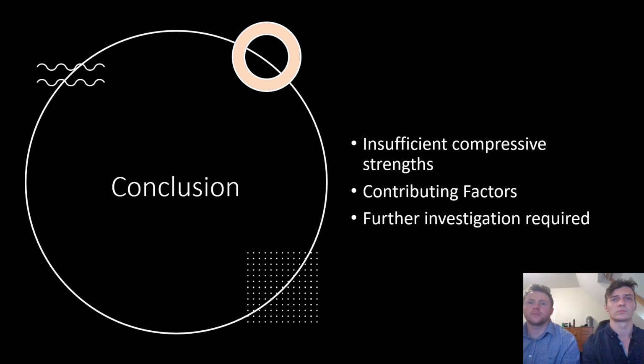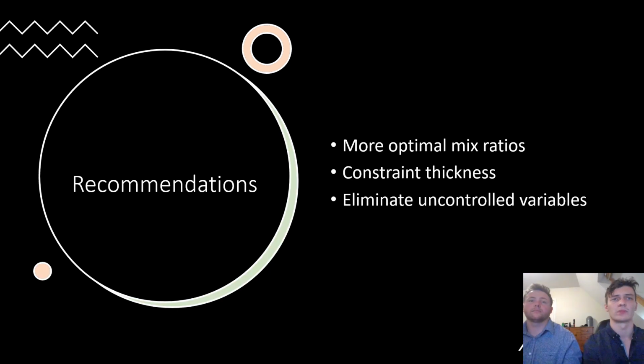The compressive strengths obtained for all no-fines concrete unconstrained and constrained mixes did not meet the required compressive strength of 17.5 MPa as per NZS 3604. However, there were numerous contributing factors that likely influence the integrity of the results, including curing method, mixing technique, material quality, and unavoidable human error. Recommendations are supplied for further investigation, with the results obtained, although insufficient, showing potential to be viable.